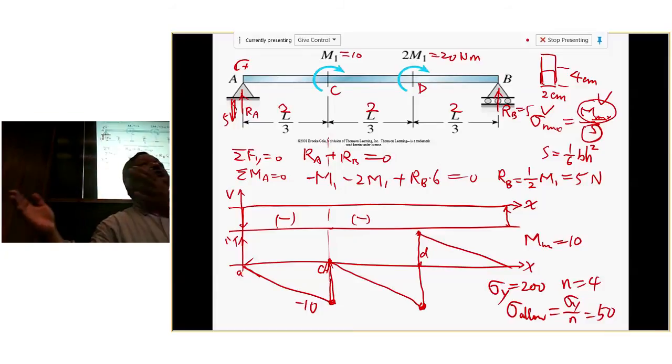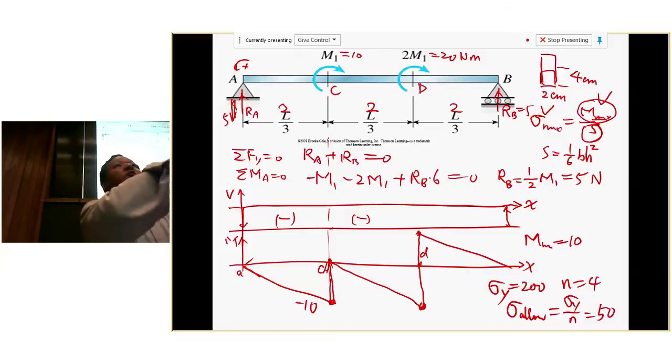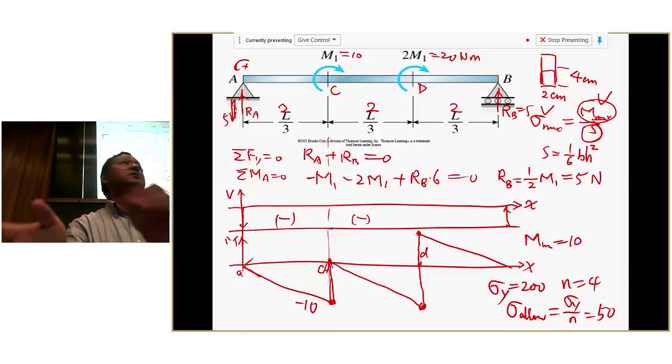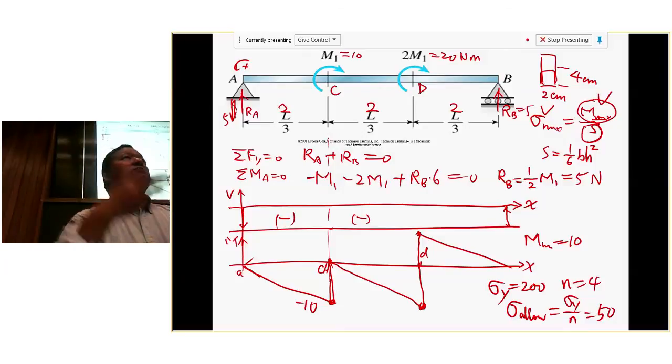It's similar to chapter 2. When you have a cable, you know the material, you know how much stress it can take, and then you determine how much load you can apply. So it's similar, three types of questions: determine the maximum load you can carry, determine the maximum stress at the given load, or determine the dimension you need to carry the load. Those are all three types you should be able to handle. The relation is the same; it just asks for different variables.